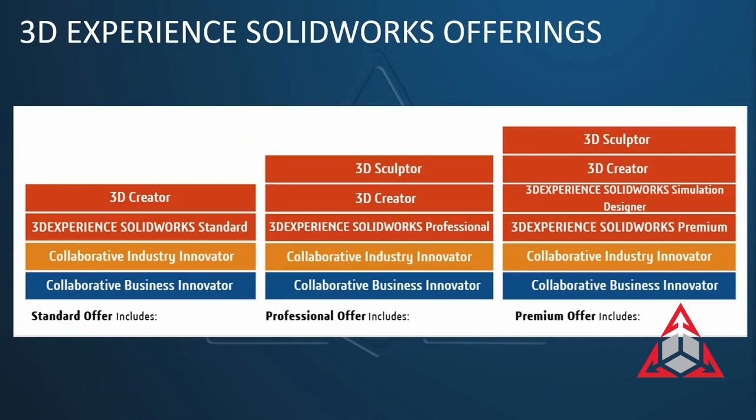You can pull that model into SolidWorks and build other mechanical parts around it, and you can still add to it. But you're going to see it almost like a dumb body for the initial thing, but you can add to it inside SolidWorks, add features to it. Those files cannot be edited, just added to, from within SolidWorks. You can still edit them back in XDesign or Xshape, the 3D Sculptor, 3D Creator roles on the cloud.